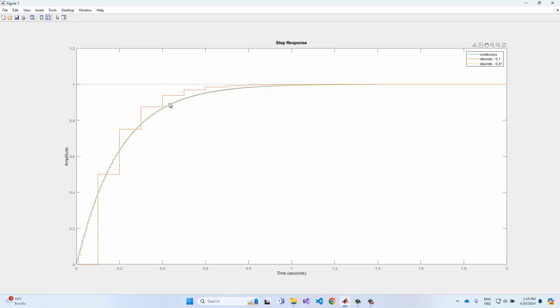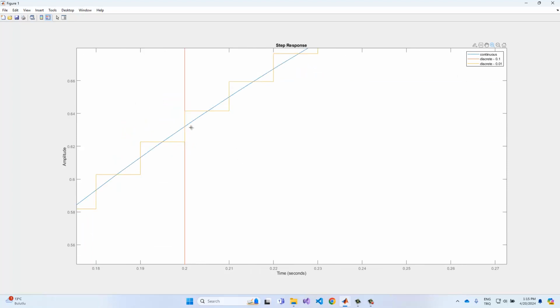that with 0.1 seconds in here, there could be some mismatch between the continuous and the discrete one. But see that if we sample the signal based on this information, the error between the continuous and discrete is diminishing, right? Because if we take data at a sampling period of 10 milliseconds, we can converge to the continuous results. But maybe this is not possible, because in your microcontroller structure there could be many codes to be implemented in your system.